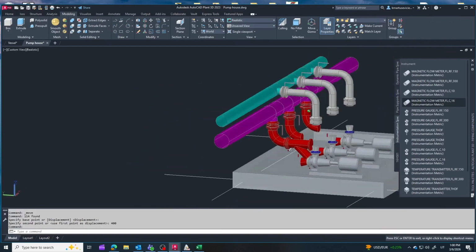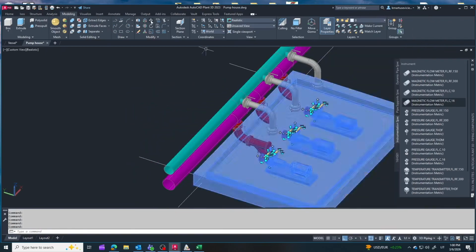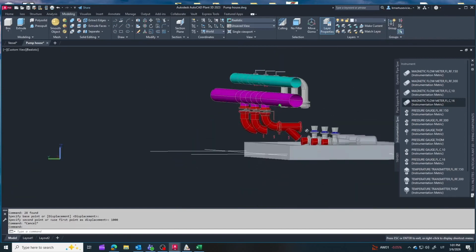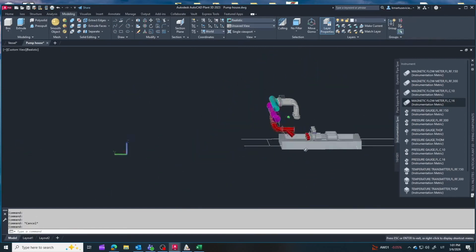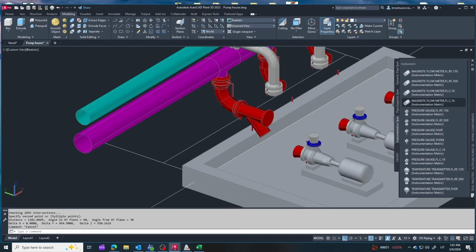The pumps also need to be raised from the floor because we need space for the piping components below. For this installation, I choose a concrete foundation for the pump unit. In other situations, metal frames can also be used.